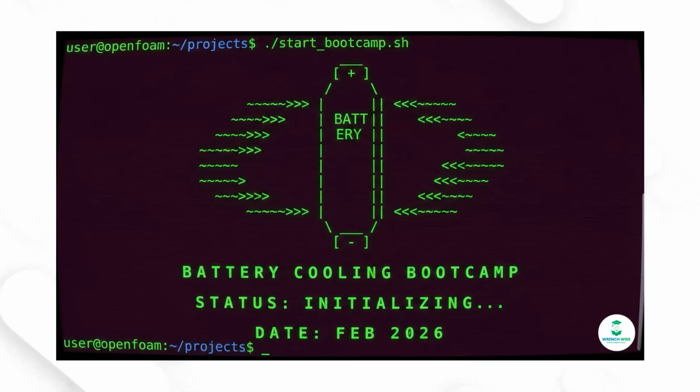The next webinar is on Friday. In a similar fashion, we will talk about radiation heat transfer. Radiation becomes much more relevant when your temperatures go higher than 400 degrees Celsius, which is generally what happens during thermal runaway. If you experience thermal runaway in your battery pack and you don't account for radiation heat transfer, you will vastly underpredict the temperature or localized hotspots within your battery pack.